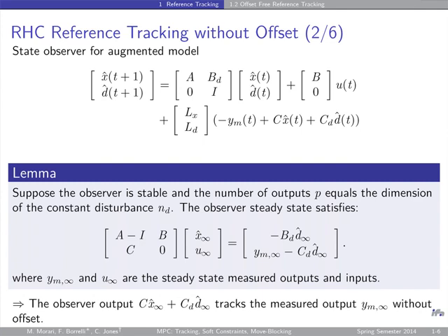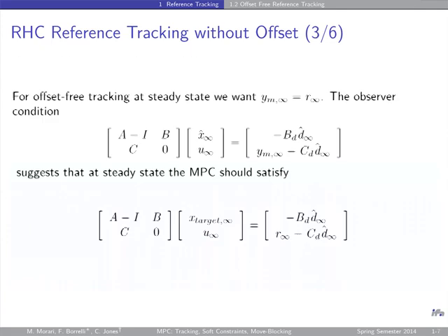In general, you have two types of constraints. One constraint is on the inputs, the manipulated variables. What are those? I mentioned those are, for example, valves in some pipe that can go from completely open to completely closed. Or some voltage supply to some motor that has a maximum possible voltage that you can apply, between 0 and the maximum voltage. So you cannot go higher without destroying it. You cannot open the valve once it's fully open. So those are hard constraints. There's no little bit more, a little bit less. The input constraints are usually hard.